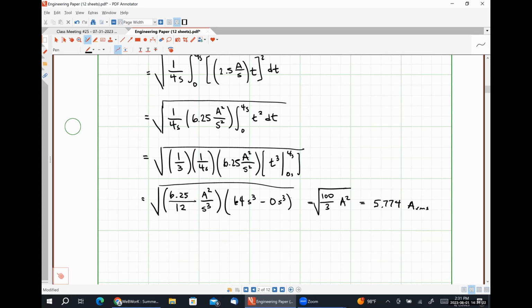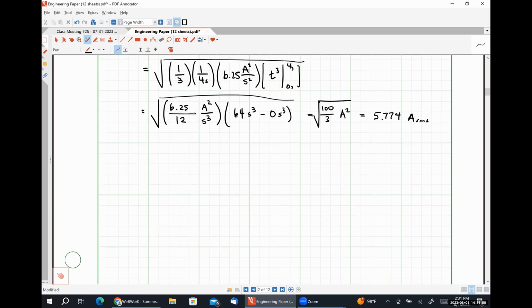So it really doesn't matter what type of waveform we have, voltage or current. The only thing that we need to know for sure is that it is a periodic function. If it is a periodic function, we can find the effective value of it by simply applying our RMS equation, where we take the root of the mean or average of the square of the function. Okay. So we did two arbitrary periodic signals here. Let's do one last signal.